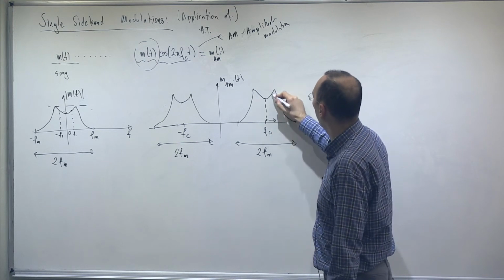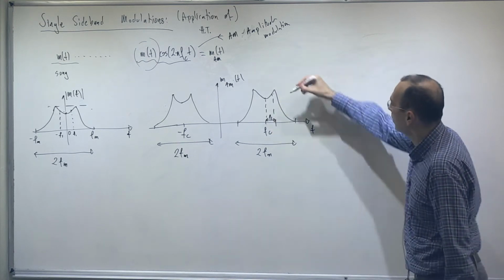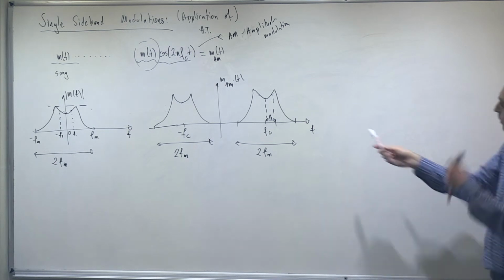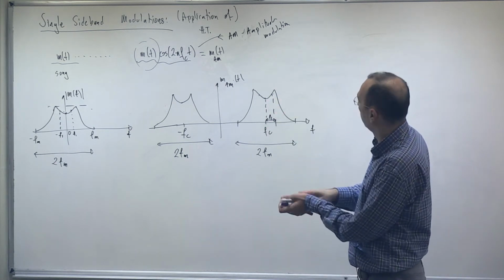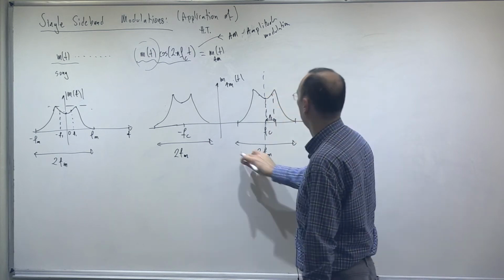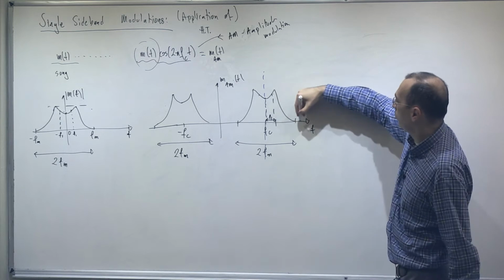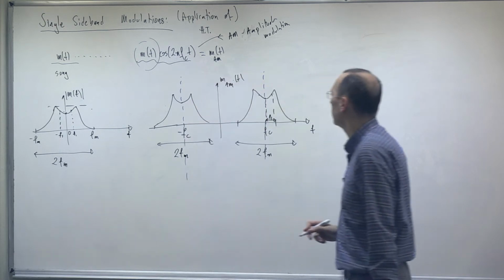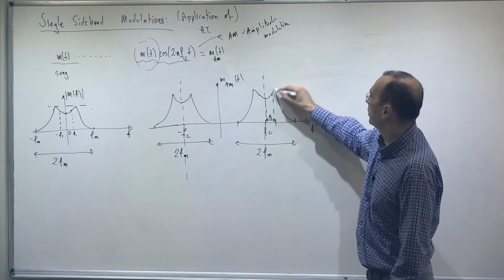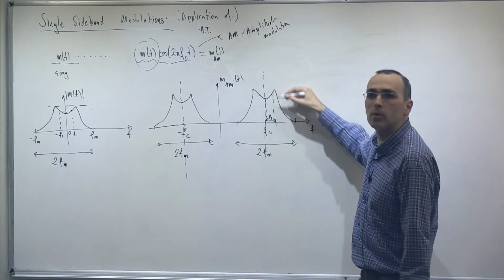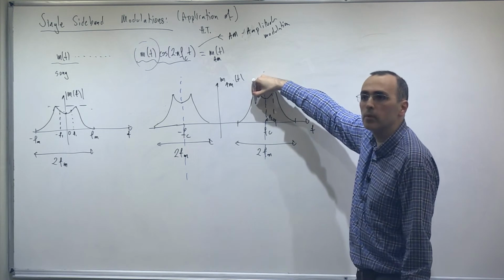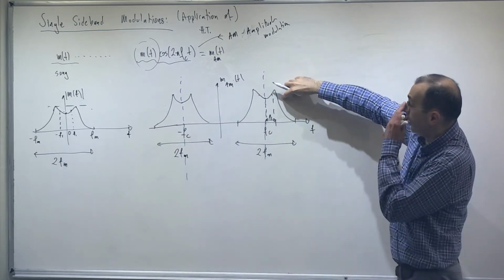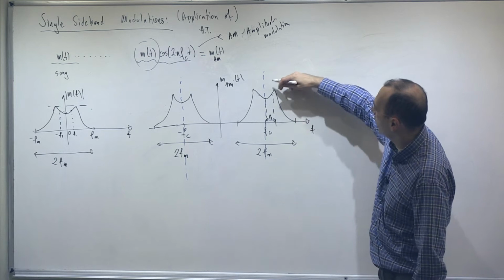So let's say f1 units away from the carrier frequency, I have the same situation because it's nothing but a shifted version. Now you can see that I'm not using the spectrum very efficiently, because half of the spectrum in this bandwidth is sufficient to find the other half. Now one idea to increase the efficiency is to send only the right-hand side, this upper half, or only the lower half. And then somehow, if I can reconstruct this signal, I'm done, because this upper half contains the same information as the whole signal.